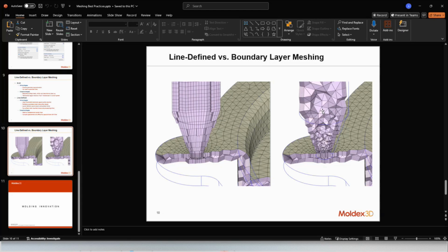And if it's happening through the thickness, then we need to make sure that the solver is continuing straight down in a line of elements. And if there's a disruption, these tetrahedral elements are quite poor from a computation standpoint, and they create a disturbance in the solver.